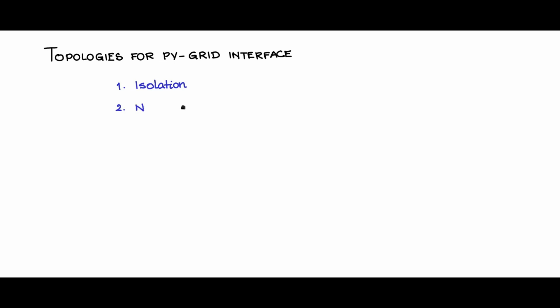There is also classification based on the number of power stages. So you may have one power stage, one DC-DC converter to take care of maximum power point tracking for the PV modules, source modules. There is another DC-DC converter which can be used for current control or voltage control of the output.